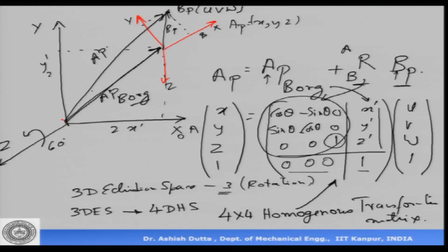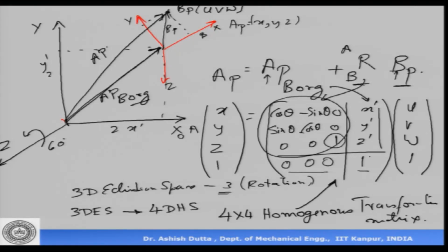In today's class we discussed the homogeneous transformation matrix, and the important thing is that you need to know its structure, which is very, very important. In robotics, apart from doing all the mathematics, like matrix multiplication, we have to correlate that to the actual robot. When the robot is moving, we should know exactly which part of the homogeneous matrix corresponds to the rotations and which part corresponds to the translations, and then we will be able to write the homogeneous transformation matrix very easily. In the next class, we will look at multiplying these matrices to get the final matrix,